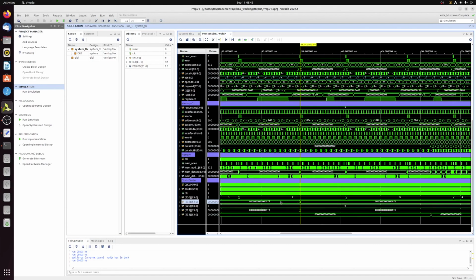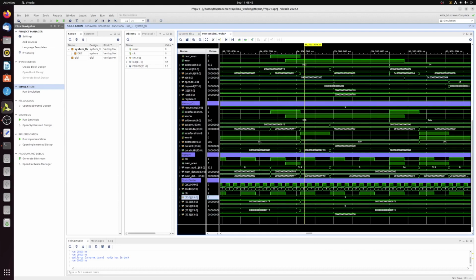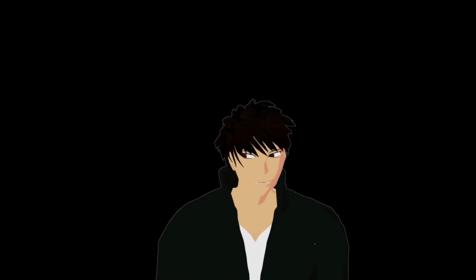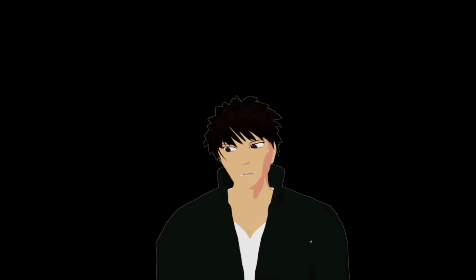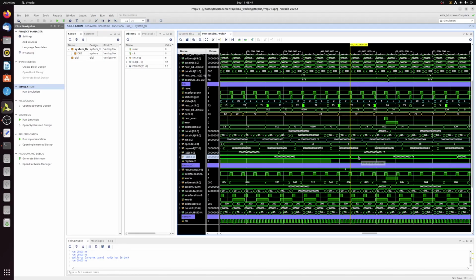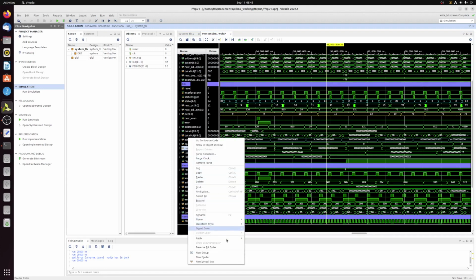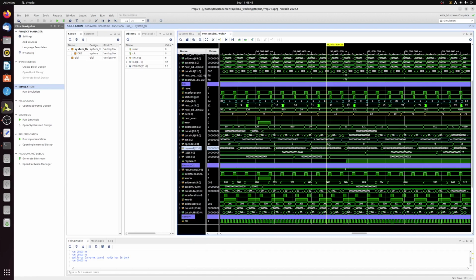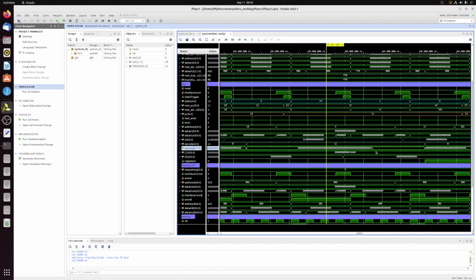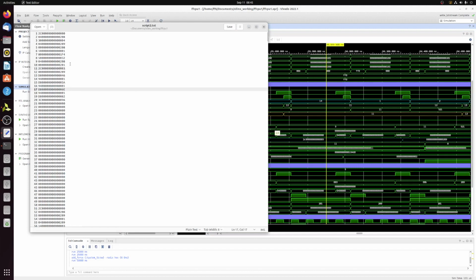The peripheral memory address matches the LED output, so I go and I look at the ALU next, and this output value also matches. So then I have to go through the fetch, decode, execute cycle for each instruction in this part of the program that calculates this value. And here, the switch values are read improperly, but the third switch value is being masked out. And you can see that the payload, which contains the bit mask, was set to 3, which is binary 0, 1, 1, and it's supposed to be set to 7, 1, 1, 1. Fixing that in the code fixed the red LED issue.